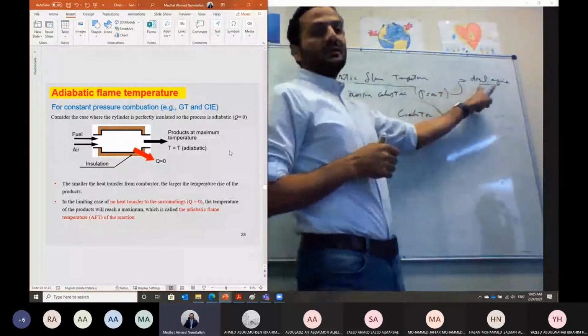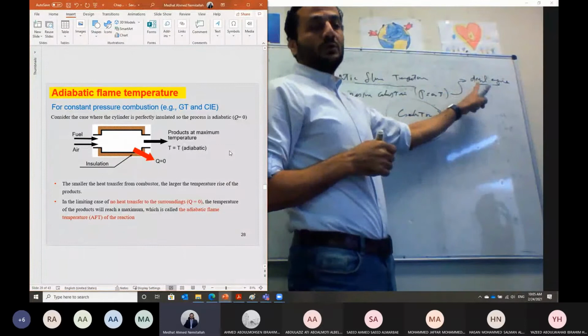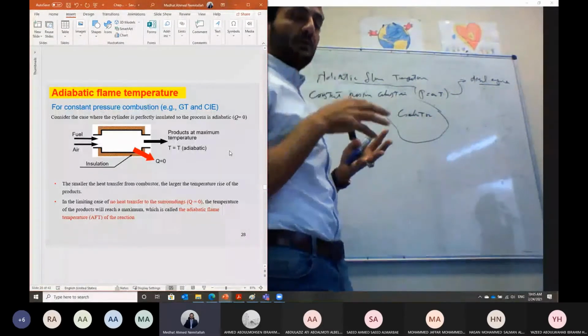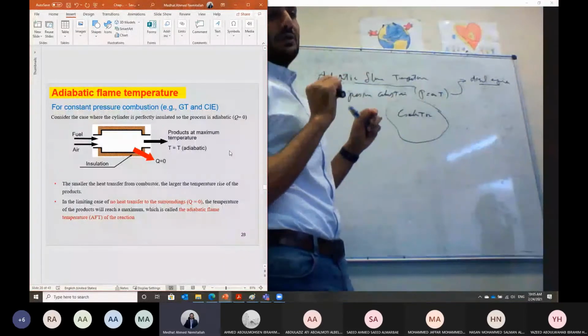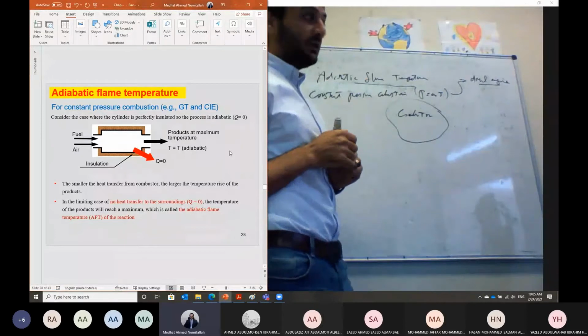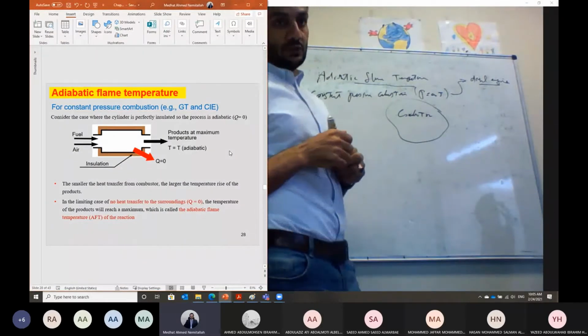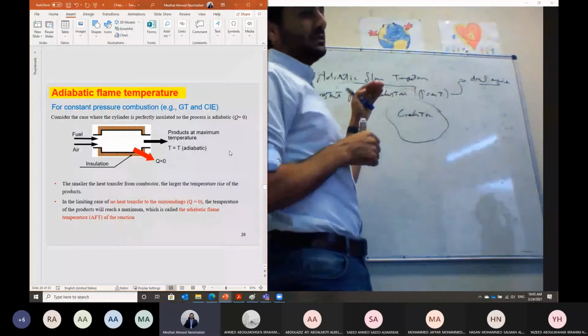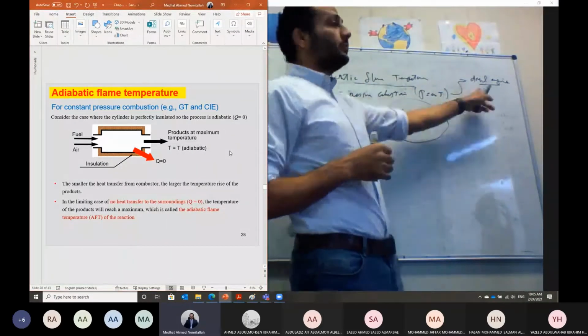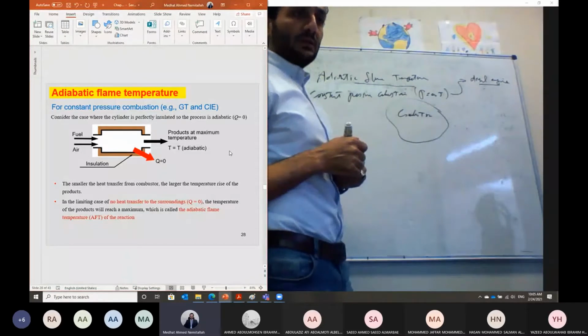And this is unlike the case of a gasoline engine. Usually in a gasoline engine, we have instantaneous combustion. Once we have a spark, we have this combustion at a given location of the piston, so it usually occurs at constant volume. But in a diesel engine, as we said, the fuel just needs some time and the piston will be moving, and in this case, we can consider the pressure inside the cylinder is constant.